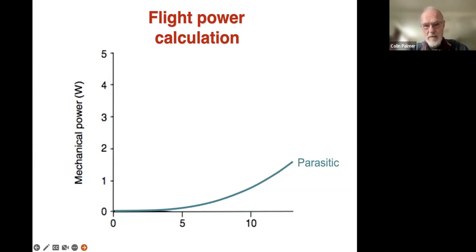However, it's also generating lift, and lift doesn't come free. Lift has a drag penalty associated with it. It's called induced drag. We don't have time to go into it today, but it's all to do with that vorticity I showed you earlier, that vortices can't exist in isolation. So actually the tips of wings shed vortices, and they're wasted energy. There's nothing you can do about that. That's basic physics. You can reduce it, and there are ways of reducing it, but ultimately it's still there.